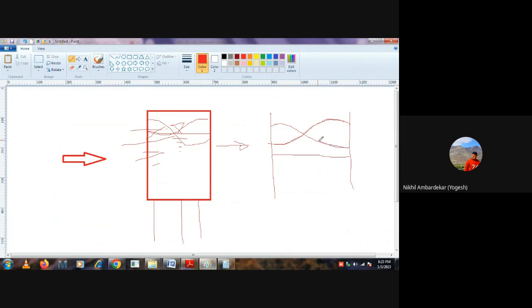So during that time, this water pressure, this figure or wave of the water, will be acting like this on the wall. Yes. So this upper portion will be considered as a convective mass, which I call MC. MC means convective mass. But somewhere at the bottom or mid of the tank, this entire volume of the water will be constant. Okay, so this zone will be considered as an impulsive zone.